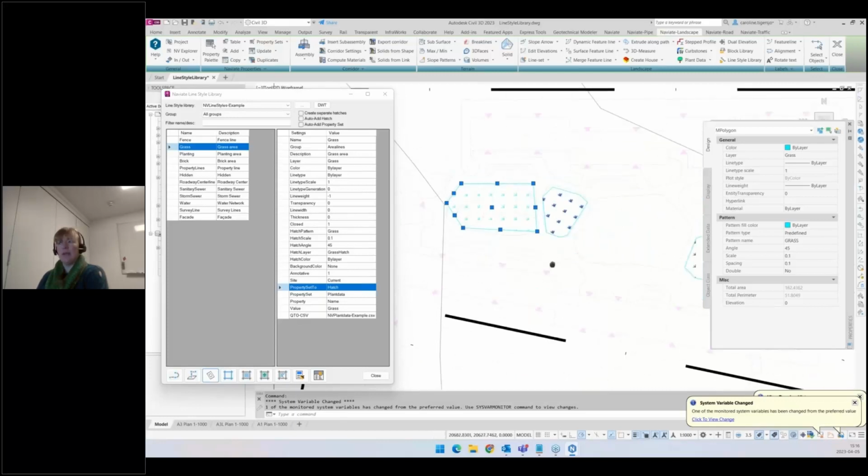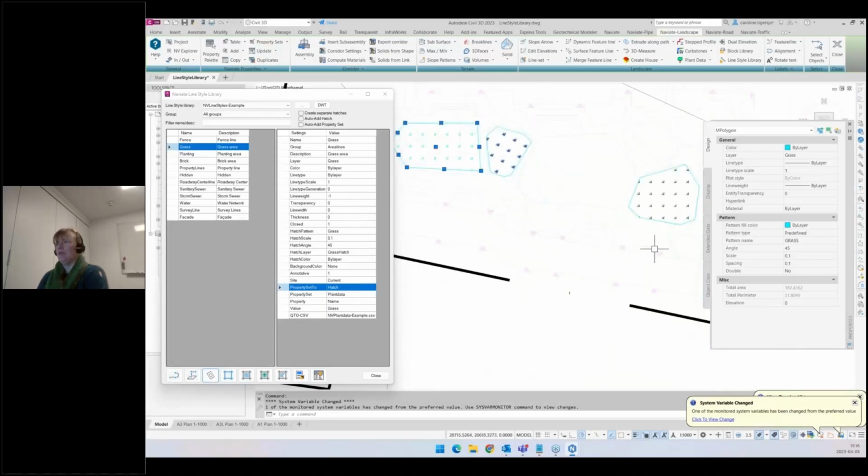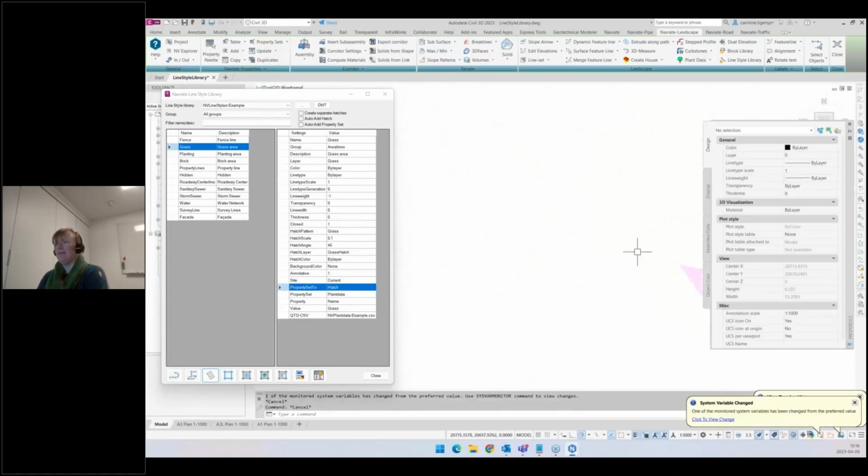These are standard AutoCAD objects, so it's not something that we have magically discovered here in Symmetry, but it's actually an AutoCAD object. The last one here is a B poly, and this will become an ordinary polyline, but it's a way of creating a polyline from boundary objects. So if I have an area that I want to create a closed polyline for, then I can do a B poly.